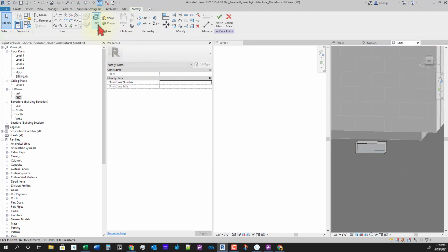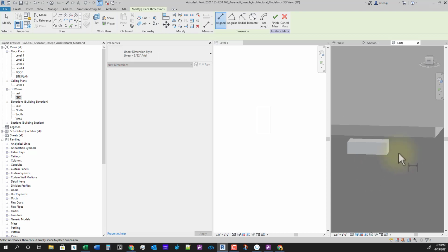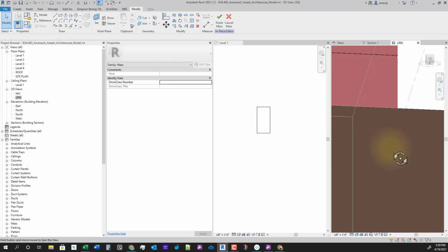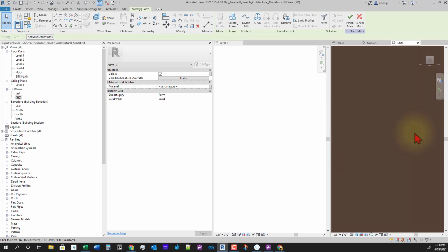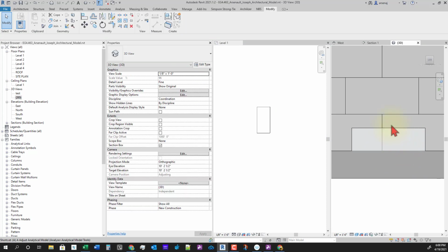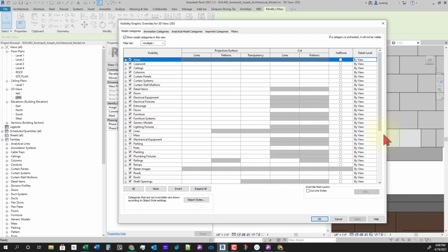And let's set our work plane. So up here at the top, set the work plane to the bottom. I'm going to throw on a dimension, hit DI for dimension. Try to get this. Actually, here, maybe this might be an easier way. Select this block, hit left, and basically go ahead and hit finish mass. And I'm going to hit the align tool. I'm going to try to align to the block beyond here.